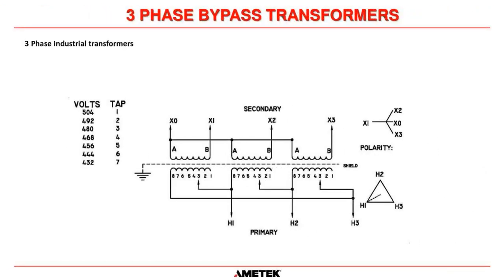Here's a three-phase transformer, 480 to typically 120/208. And again, we've got taps on there to select the proper voltage. Oftentimes these transformers go in and nobody bothers to look at the taps it's set on, and maybe they're set up because the 480 bus doesn't run 480 volts. Maybe it's only, again, 460, 465, something like that. So the output voltage is already low coming out of the bypass transformer. Maybe it's down to 116 volts, something like that.